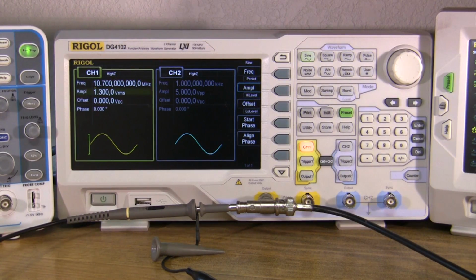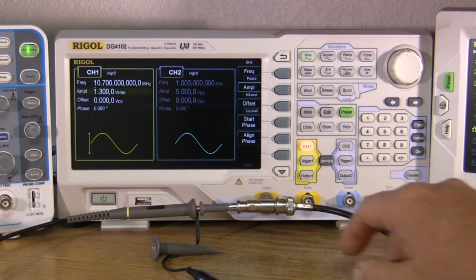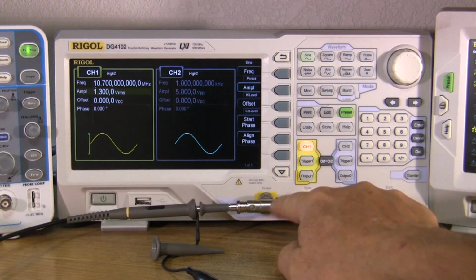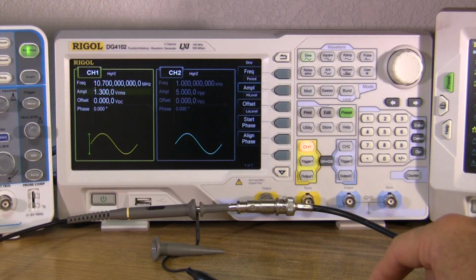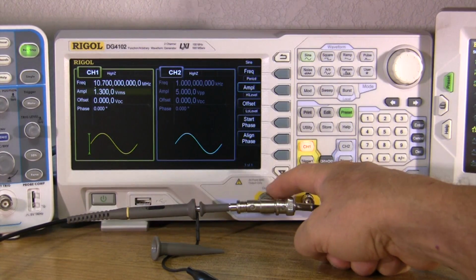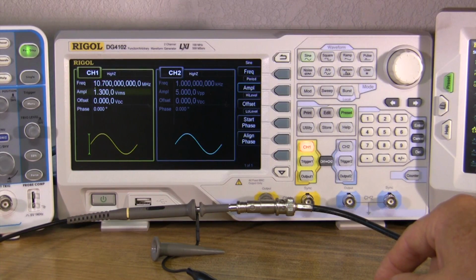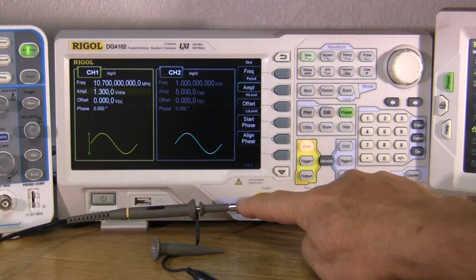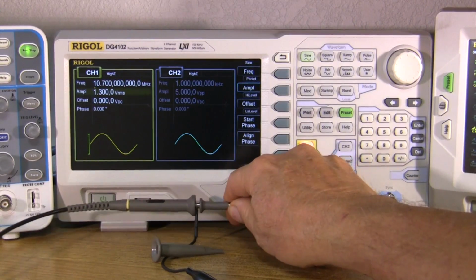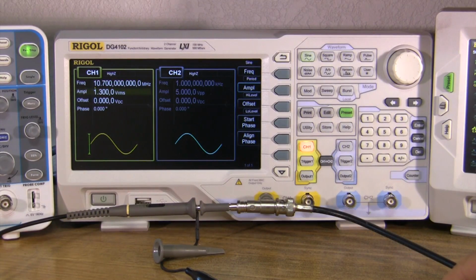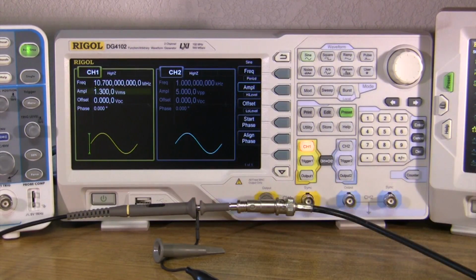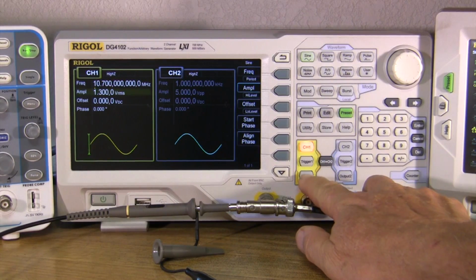However, I want to point out something here that I wasn't fully aware of. I have the spectrum analyzer over here hooked by this cable, and that cable happens to be a 50 ohm load on the spectrum analyzer. The source here on this T connector is the output of this generator, which is actually 50 ohms as well, roughly. And so there will be some attenuation of the signal because it's being divided, which will be viewable on the scope, which I have attached here on the other part of this T. We have no output at the moment because this output is not turned on. So I'm going to turn that output on.